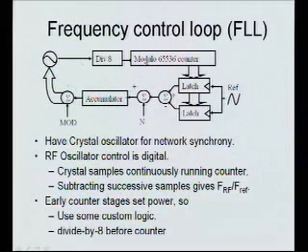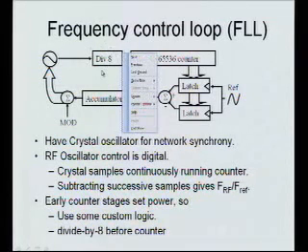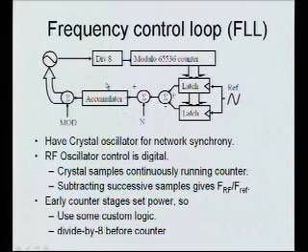Now, when you design this, most of this is just low frequency digital. It's all running at the frequency of the reference, which in this case was 32 kilohertz, I think. So really low frequency. There's no power there at all. But the one place where there's power is in this initial divide down. When you're counting cycles of the oscillator, you're counting a gigahertz signal. That requires fast digital. So I spent some time doing some custom digital design to try to cut that power down. Particularly in the very first count, I put in a specialized divide by 8, which takes the frequency down by a factor of 8 before you start counting accurately. I'll show you how I implemented that to make it very low power.